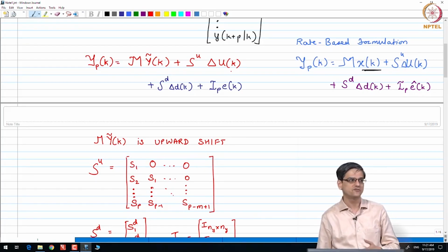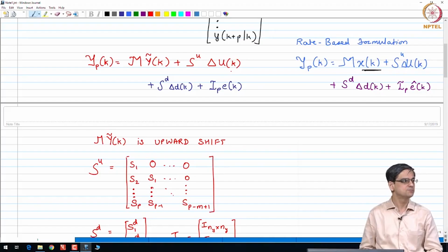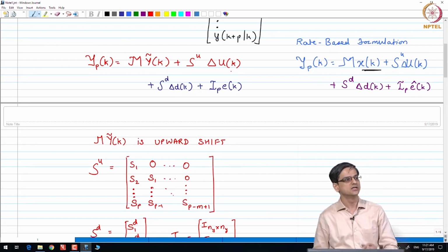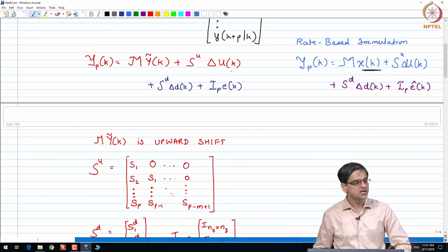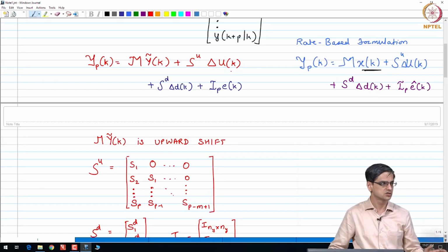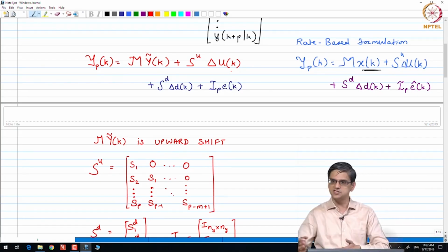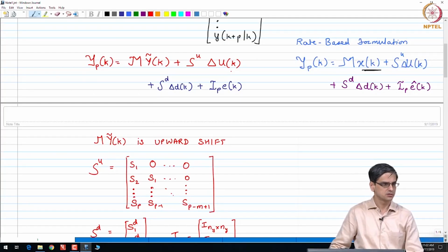It is also not relevant for a problem like inverted pendulum, because you do not use step response MPC for control of unstable systems. Step response is only for control of stable systems or nominally stable or integrating systems. The MPC for integrating systems we have not covered in this course. The state space MPC is an all weather friend. You can use it for unstable, stable, marginally stable, all type of systems. Again, the last 2 minutes was a segue in response to that question. Just keep that in mind.